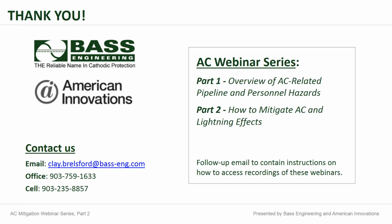So there's a switch in that coupon head. It's a normally closed switch, and it's spring-loaded, but as you depress that switch, you're disconnecting the coupon from the pipeline so that you can get that instantaneous disconnection and thus that polarized potential associated with that coupon. So hopefully that answers your question on the DC side of the picture.